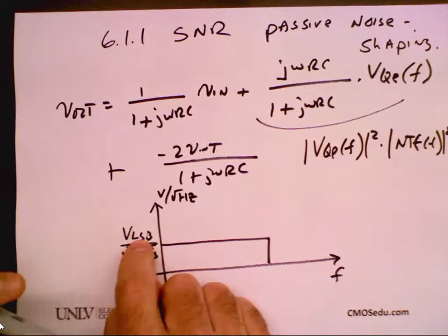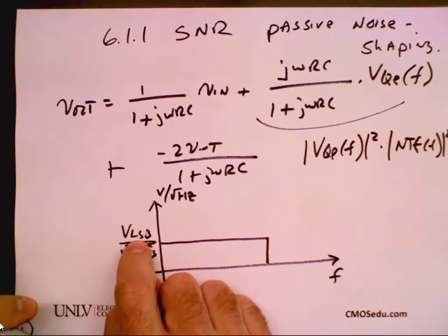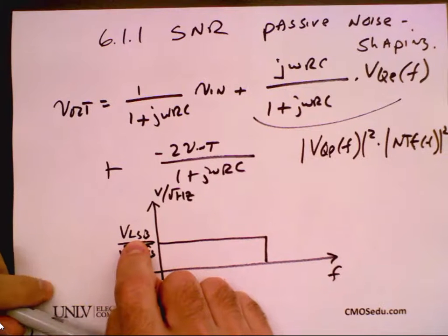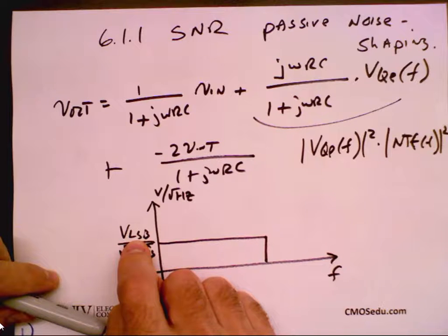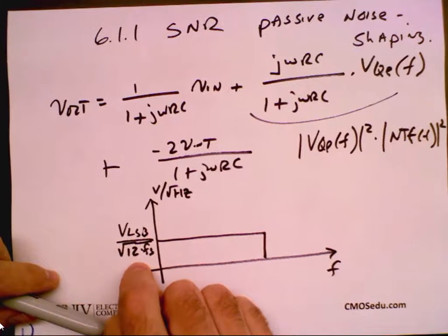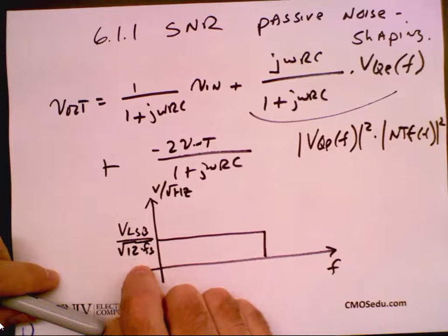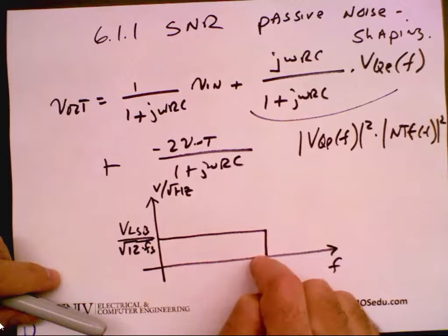Okay, so with what we did before, we had a 1-bit quantizer. What is VLSB? Yeah, it's VDD in our example, right? Because the output of the comparator goes from 0 to VDD. Any questions? So this is relatively a big amount of quantization noise because of that.